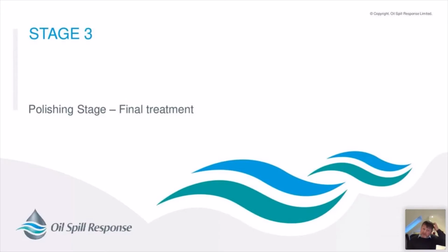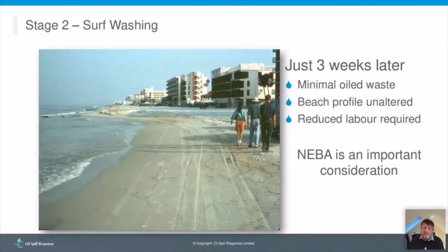Another thing we can do, which is similar to that, rather than doing surf washing, in some cases, if it's suitable to do it, we can temporarily remove substrate and take it away and basically wash it. So we can take away sand or gravel or boulders or cobbles, and we can put them into things like concrete mixers with high volumes of water, and roll them around inside for a while. That will clean off the substrate.